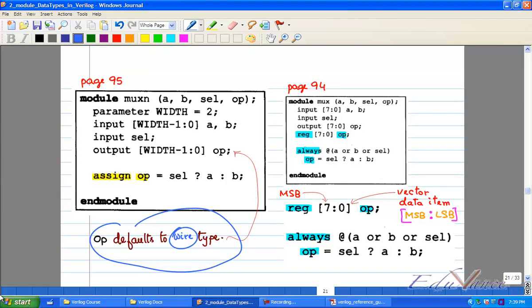One of my favorite interview questions when I take an interview for any design company, when I interview, I ask, why is sequential construct called a sequential construct? Simple. The typical answer is because the things execute sequentially. No. Yes, it executes sequentially, but at the end of the day, a sequential construct is used to design what? Sequential hardware. However, you can design combinational hardware. Okay, it is possible. That is a well qualified interview answer. Understood?